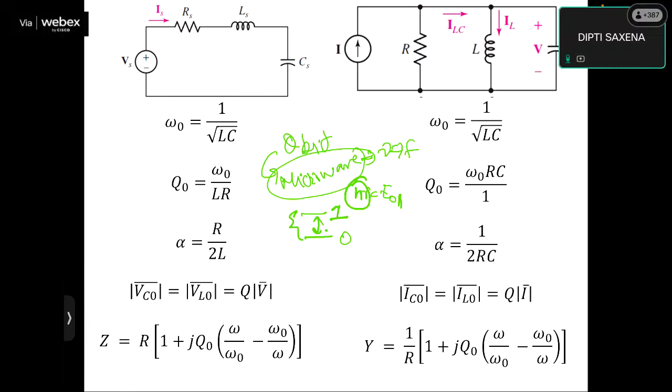We just couple an LC circuit with the qubit and we measure the resonant frequency. If the qubit has an effect on the resonant frequency, that is, if the resonant frequency deviates, then it means that the qubit is in some quantum state. If the resonant frequency is the same as that of the LC circuit, it means that the quantum state of the qubit is the zero state. So this is all about the resonance.